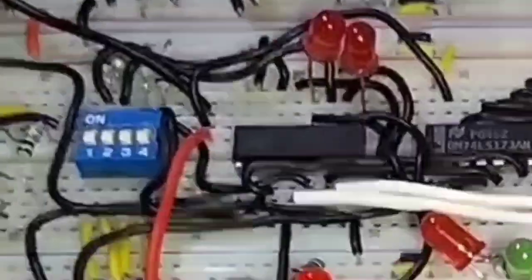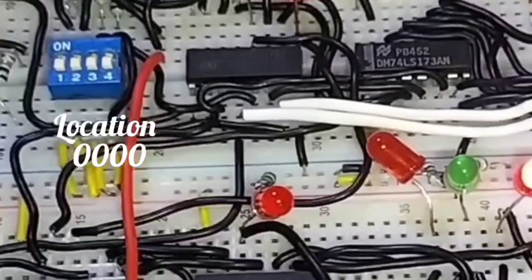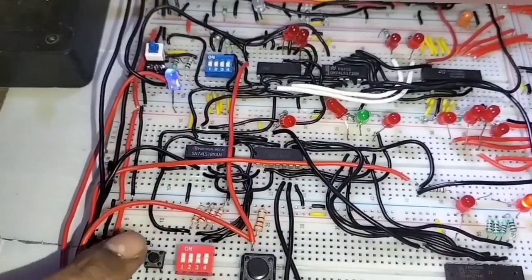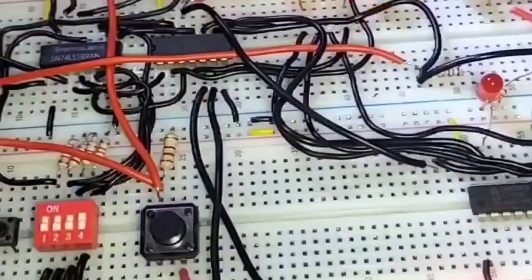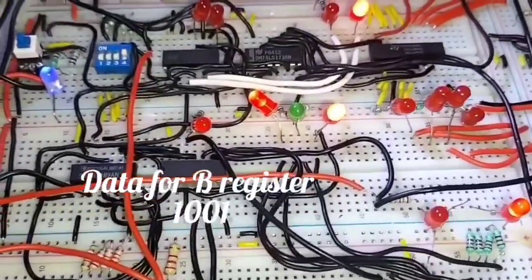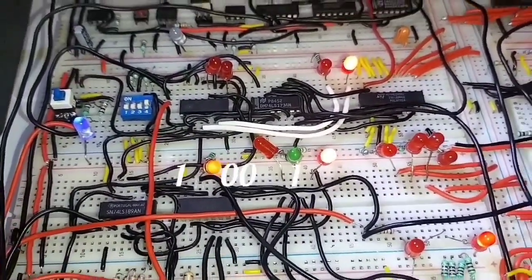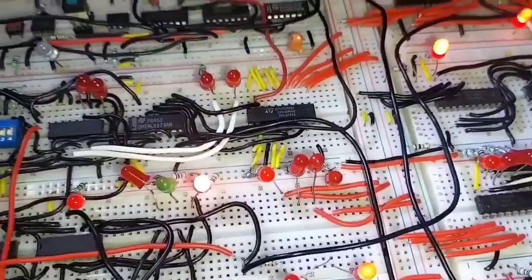Let's program for the load B instruction execution. At location 0 we stored the 1 and at location 1 we stored the data 9, which is 1001 in binary. For step 0, counter out and RAM address in micro instructions are active. This is the beginning of the 4-bit breadboard computer.